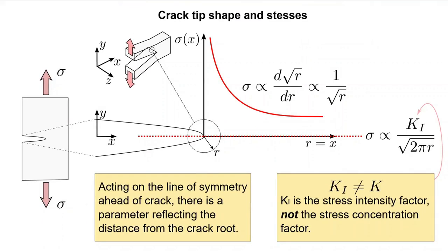Where we left off last time was with the concept of stress concentration as it applies to flaws which can occur in a material. These flaws cause the stress to increase fairly dramatically near their edges, concentrating the far field stress, that is, the stress far away from the flaw, up to some maximum point at the flaw's edges. We know that when this is taken to an extreme, such as a crack which has a very small tip radius, the stress concentration factor doesn't make a whole lot of sense anymore, as the maximum stress approaches infinity.